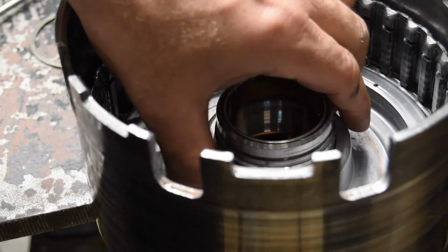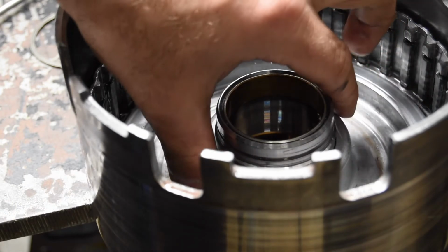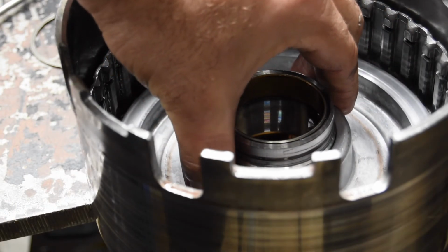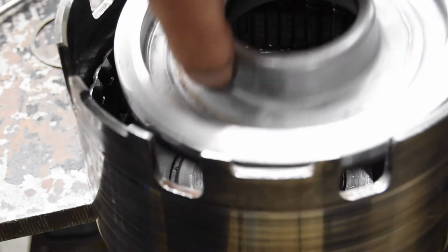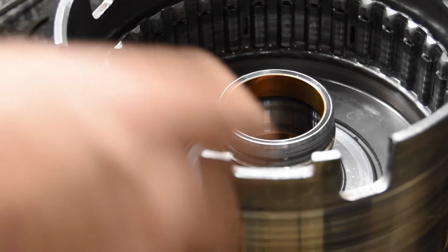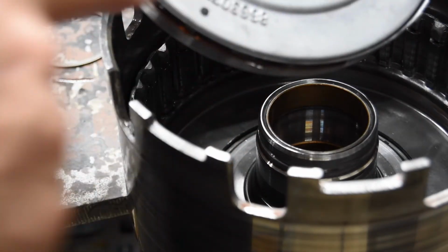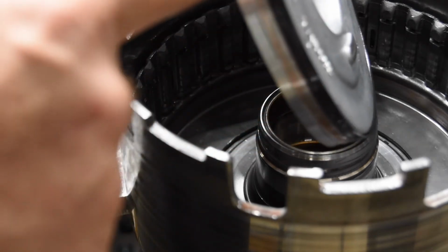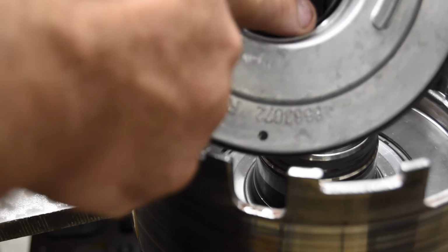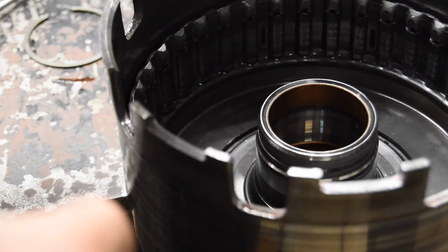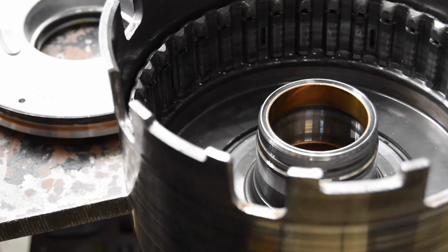And then from there, on this piston, you normally can just grab the piston and pull it up out of here for this reverse input clutch. So you can see I'm just going to pick it up, pull it right on out. And then we see down inside the drum, we see our piston. We've got a rubber seal here on the outside. Okay, we've got a rubber seal there, and then we have a rubber seal on the inside. And we'll be taking these off and getting a much closer look at them.